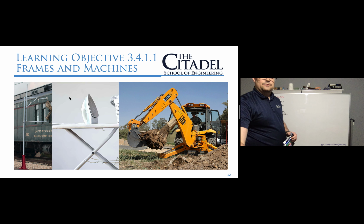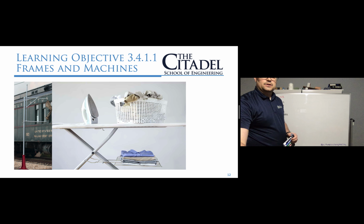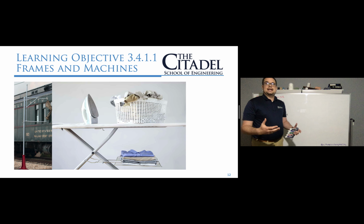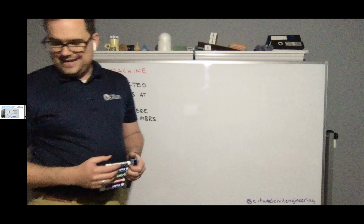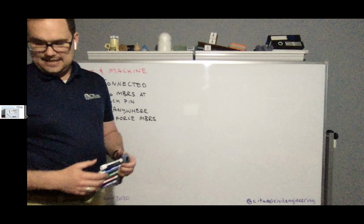Similarly, for the ironing board picture, we see that there's a load there. There's the load associated with the basket. We might model that as a distributed load. There's the load from the iron, another pin load there. And so it's loaded at a lot of different places, which is one of the assumptions that goes into our frame analysis. Now, when we do a frame analysis like this, what we'll end up doing is pulling the pins and breaking that apart.